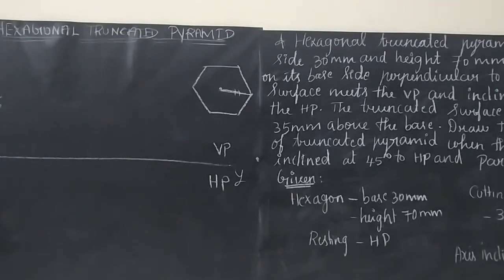Okay. So just see here, for getting this 2 and 5 you concentrate. Try to draw an imaginary line from OA horizontally. It will be cutting the line which is coming from the vertical. At this point, keep your compass here and cut an arc downwards. The arc will be cutting OC. That point is called 2. Take your compass, measure this distance and cut an arc at O and F. That point is 5.